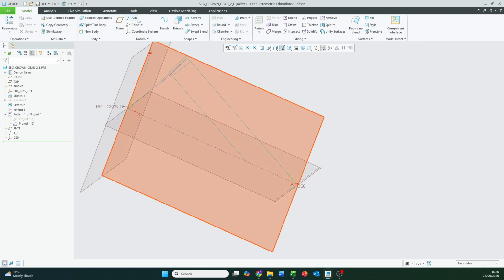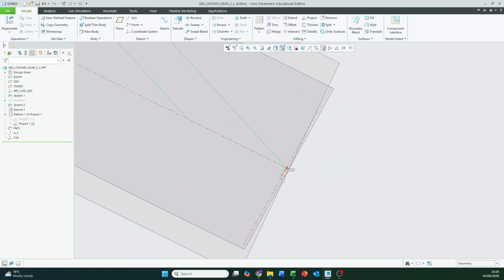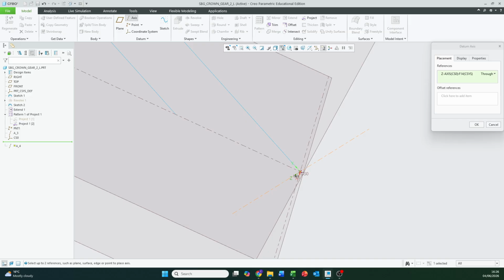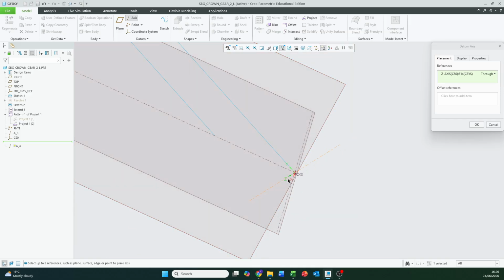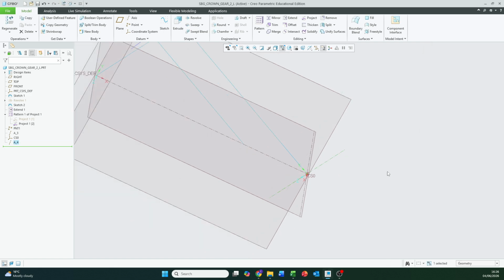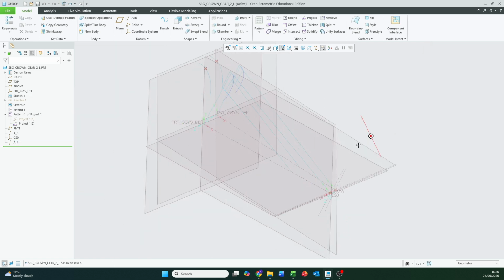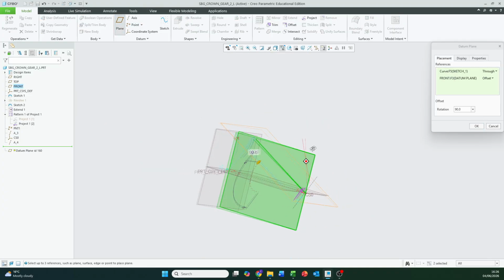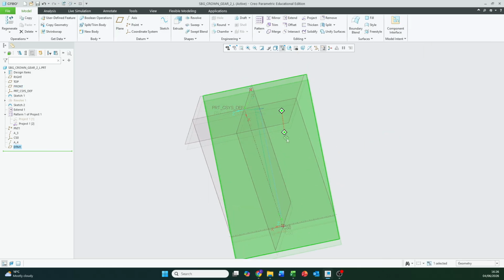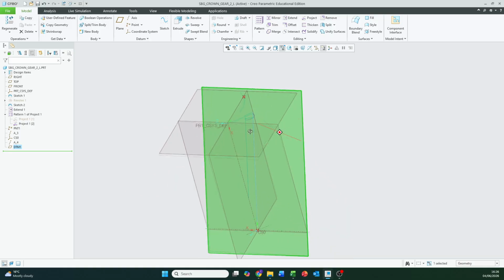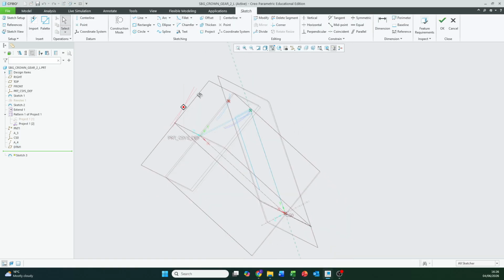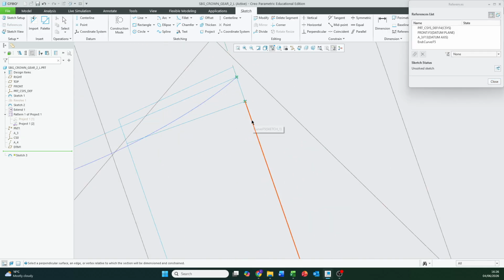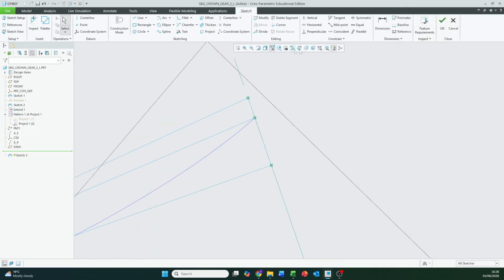All right. We can put an axis now through the Z here. I actually just used the Z-axis as our rotational axis in the previous model, but to make things easier, I'm just going to drop another axis in there. Okay, save. Next up, we're going to create that plane. Okay, that cuts through this end line here. And we're going to sketch. First off, let's reference a few bits and bobs. I want to reference you, and you. Okay, orientate the view.